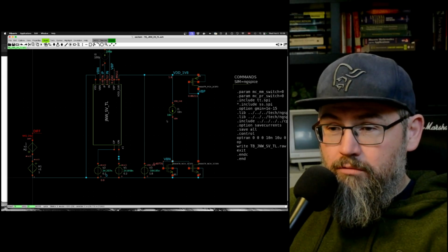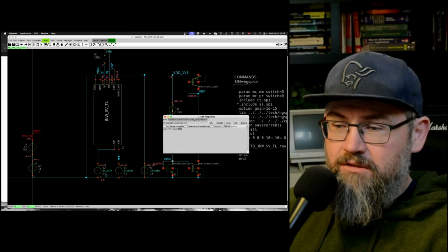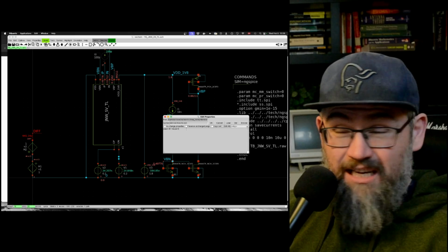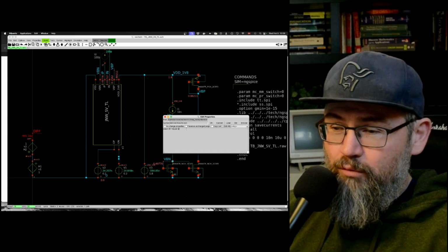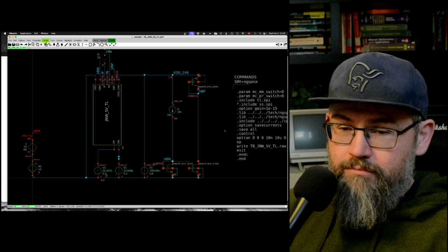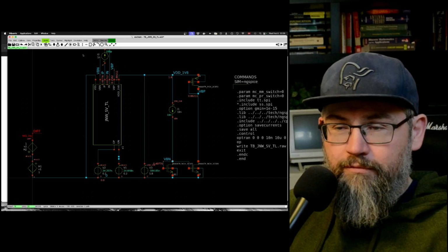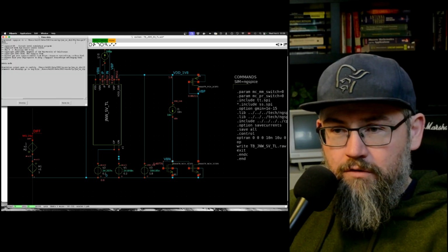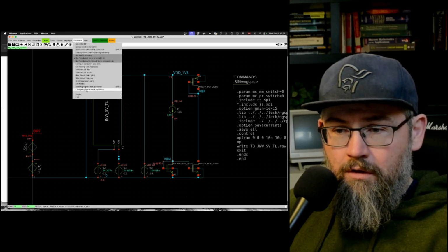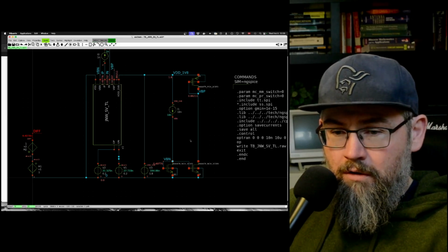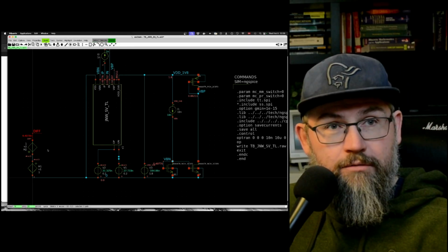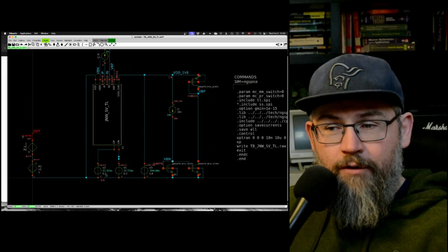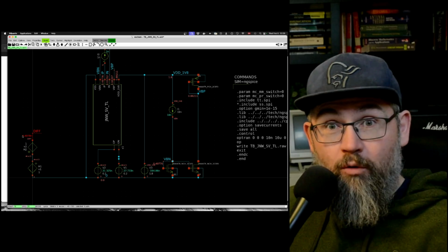Now, it's going to work up to, I guess, closer to our bias current. So that's 10 nano at the moment. So let's say I put in 1 nanoamp, which means I should get about 6.4 nanoamps out. Let's see if it still works. Yeah, 6.4. Pretty close. So you can see that the multiplication here, around 6.4, stays constant over many orders of magnitude.